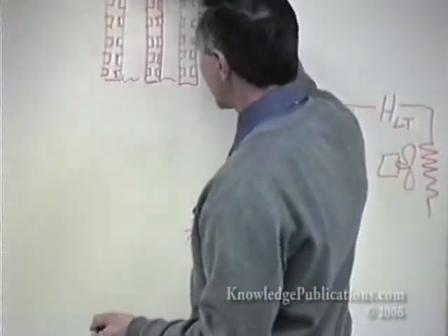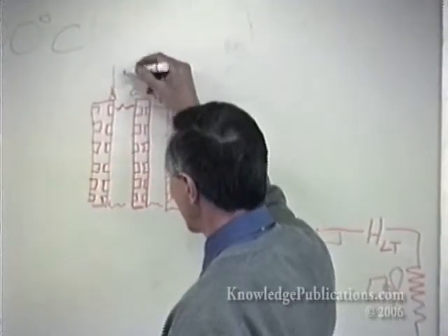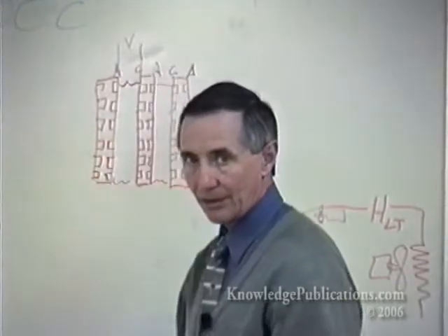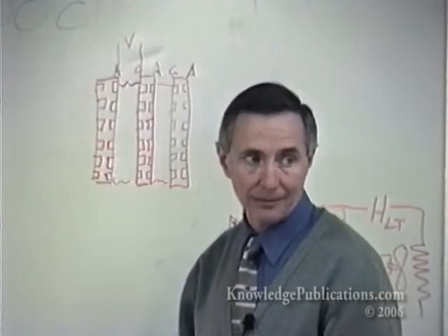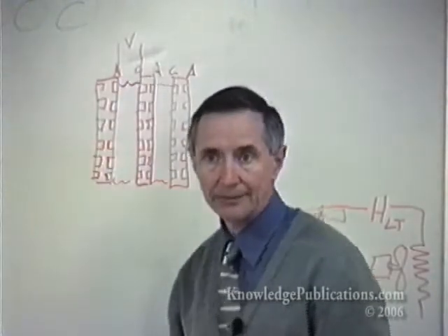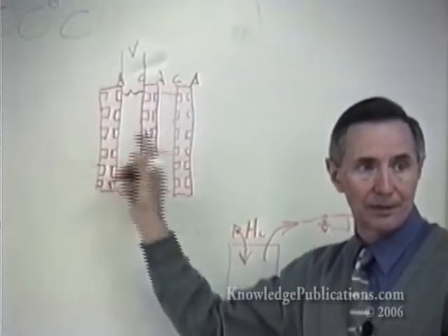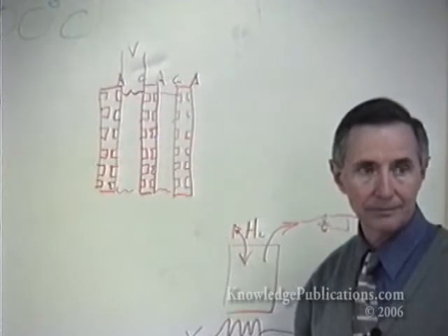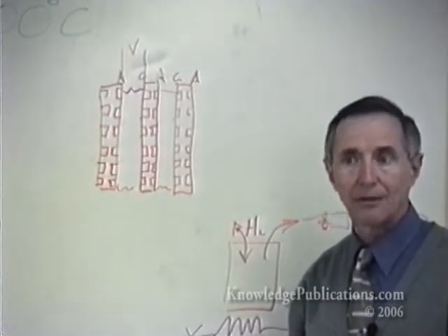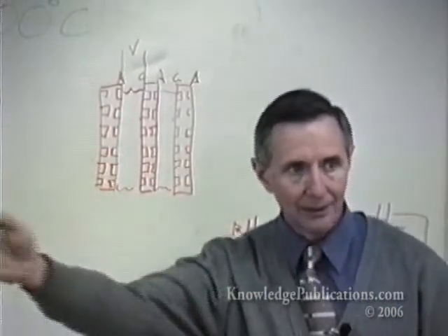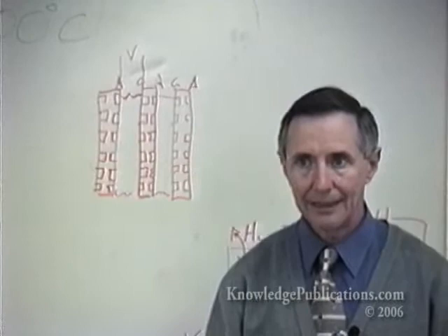Well, the way you get the electricity out is each one of these is a voltage producer. The potential between here and here starts out at about a volt, goes down to half a volt or so, maybe less. But every one of those is a series connection. You just series connect them, so the electron that you start with over here comes out at this end, but at a voltage multiplied by the number of times you repeat the unit cell. The stack size is however many unit cells you put in it and add them up in series.